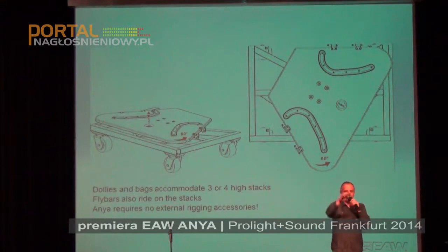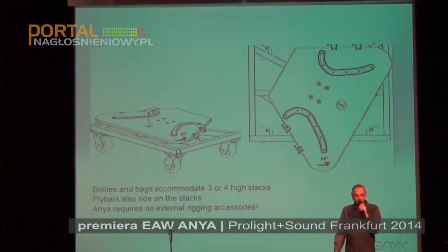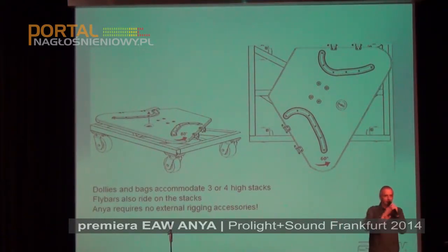Interleaf the pallets in a semicircle, pre-lock them all together, and lift them all up into the air at the same time. Once you're done, you bring them down in the same manner. They self-guide into the runners on the plates, you rotate the pallet back forward, lock it down, and send it onto the truck. It works quite well. I've been using it quite a bit.